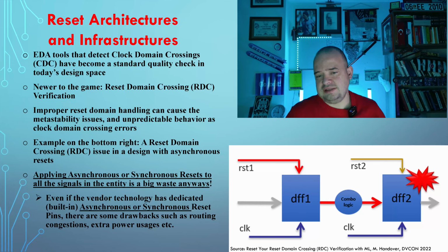Many Altera families like Stratix 5, Cyclone 5, Arria 10, Cyclone 10, for instance, and some older ones as well, have built-in asynchronous resets, both in the flip-flops in their ALMs, adaptive logic modules, and in the preliminary pre-registers and output registers inside digital signal processing units.